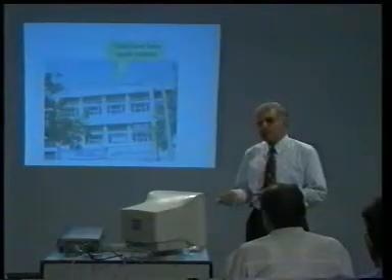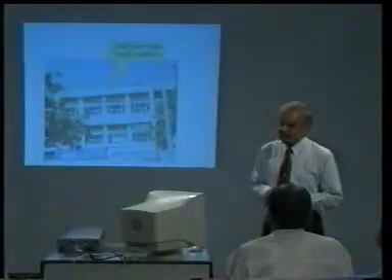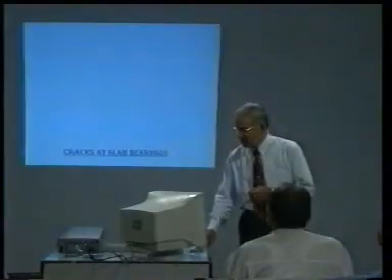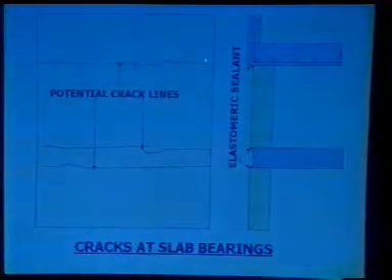Now, this is a very commonly observed sight, gentlemen. If you notice, you have a crack at this junction. Now, this crack between the parapet and the roof slab can very easily be avoided. These are the potential crack lines that you already know, the elevation. This is the parapet and the roof slab junction, and this is the edges of the lower slabs.